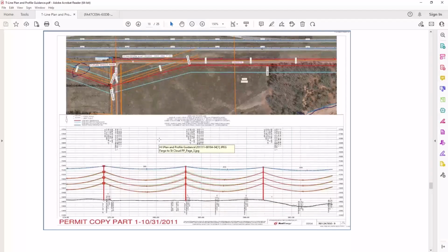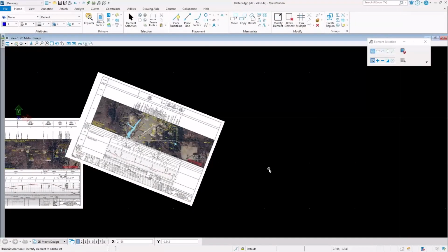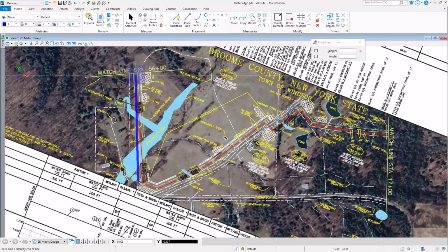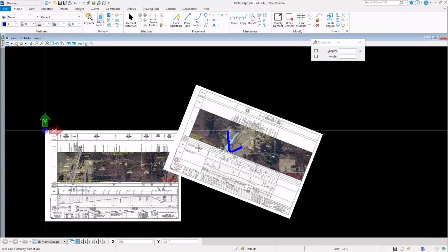So that's kind of the general information that you would get. And one way to incorporate or design your model, you can open up a CAD program and start placing the alignment drawings and plan profiles into it, so that you can simply follow the path in a tool like MicroStation and follow along with the pipeline. And you can stitch these drawings together if this is the type of information you may receive.